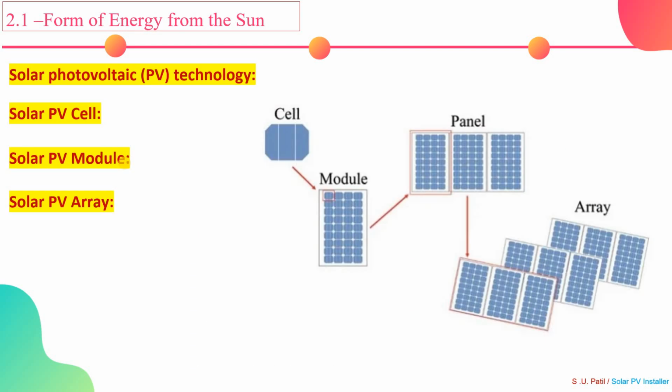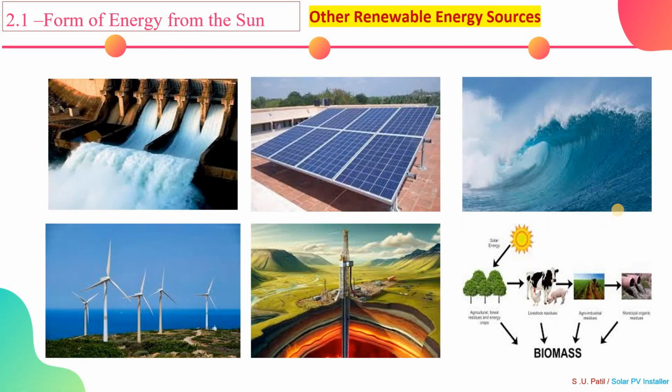After knowing the third step, now take a look at the fourth and fifth steps. The fourth step is the solar cell and the fifth step is the solar PV module. As you can see in the image of a solar cell, it is defined as a semiconductor device that directly converts sunlight into direct current, which is nothing but electricity. Now we can see the module. It consists of a number of cells which are arranged in series connection, then by connecting series connections of the arrays to form a panel, and by arranging the panels either in series or in parallel, a solar PV module array forms.